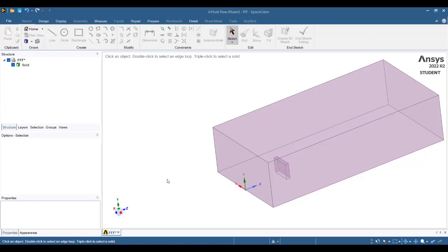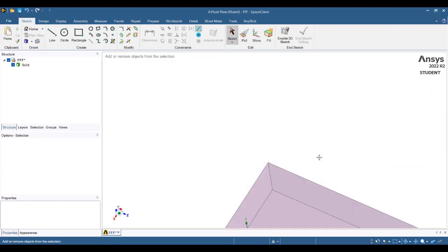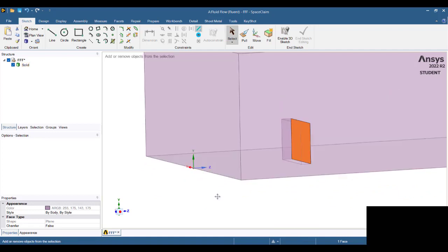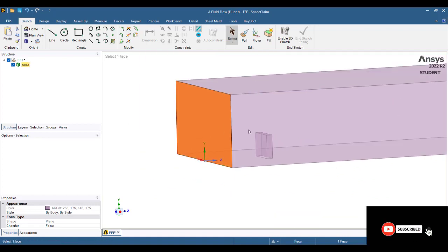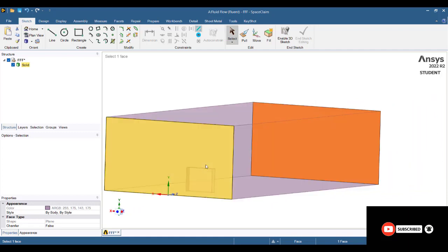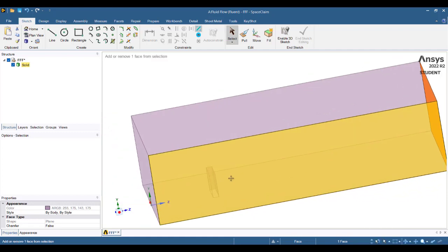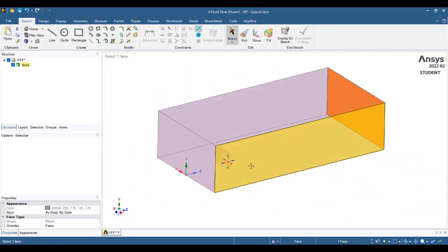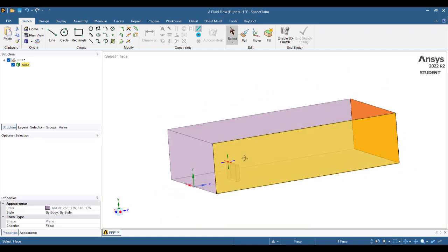In this video, we'll check how to create a block mesh or hexagonal mesh using Ansys meshing. So you can see there is a hole here, or an obstacle. From this side the flow starts going, and from this side the flow comes out, so there is a flow in, flow out, and this is an obstacle. Now we will try to define the mesh near this region, and the remaining things will be a bit coarse, using biasing.